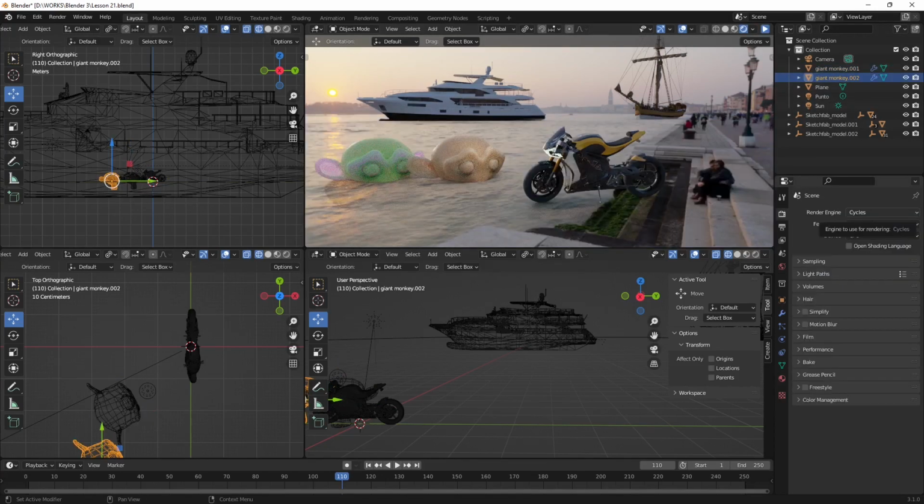Now I quickly switch into Cycles render engine because this is gonna show me a more precise result for the render. You can see here that the subsurface scattering in particular is gonna look way more accurate when you use Cycles. You can see the light coming through there and staying inside right there. And again, you can see the skin effect that I have set up.